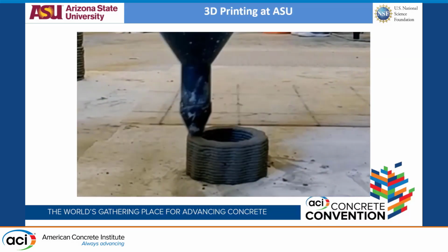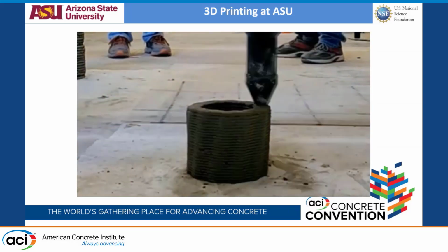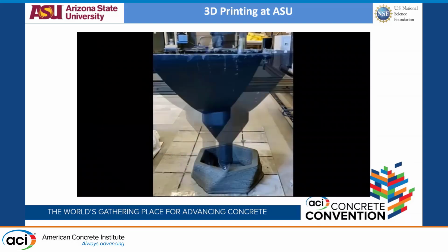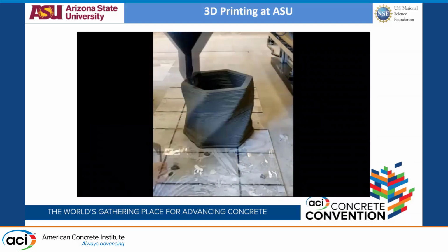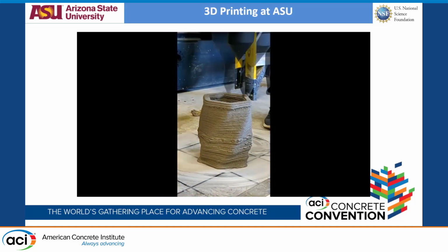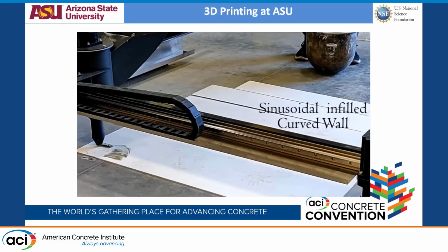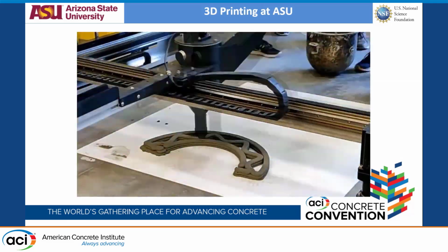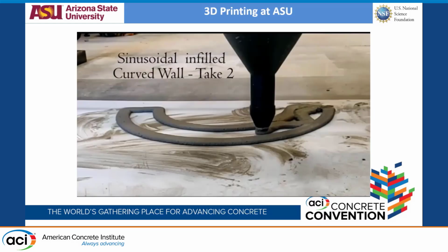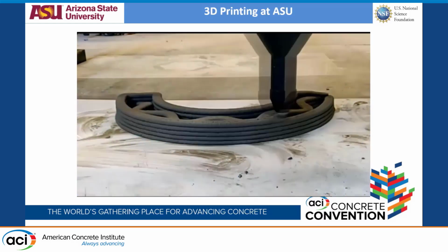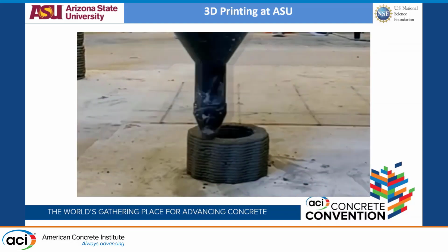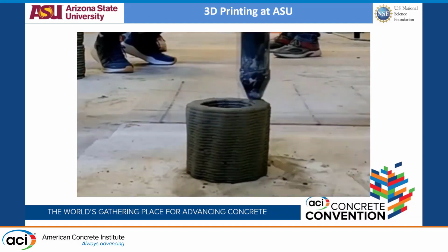So start with, again, 3D printing, free-form construction. You can construct different kinds of structures without having to actually create the formwork required for it. You could optimize your structures. You could even create overhang structures to a certain extent. Again, with all those freedoms come different disadvantages too, in the sense of layering. You have weaker interfaces and such. Basically, weakness of those interfaces usually creates a problem in the mechanical responses and durability responses of the